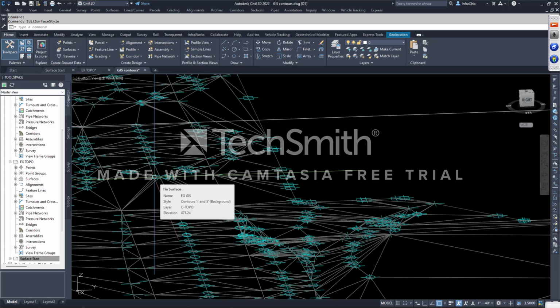It goes from the ground up. So points to surfaces, to alignments, to profiles, to corridors, to a new surface, in that order, okay? You can't go surface to point backwards and get the point to change. You must change it at the point level, which now affects the next level, which is surface. And in my alignment, if I want my alignment or my profile attached to my alignment to change, I can't change my profile. I have to go back to the surface, change the surface to change the ground profile that might be referenced along an alignment. So you don't go backwards, you go forwards. You go points, surfaces, alignments, profiles, corridors, and a final design surface. That's pretty much the build process.